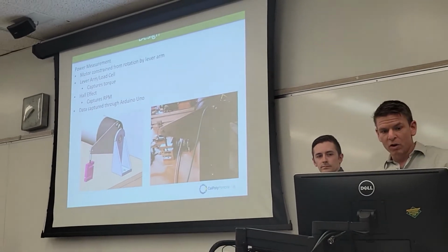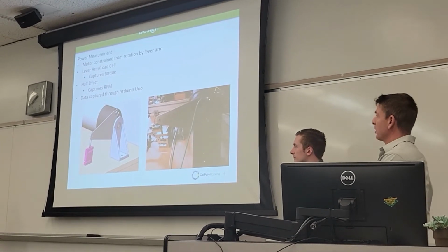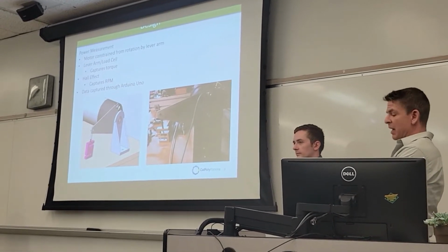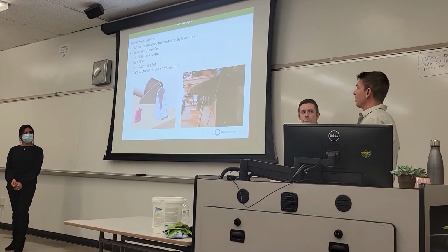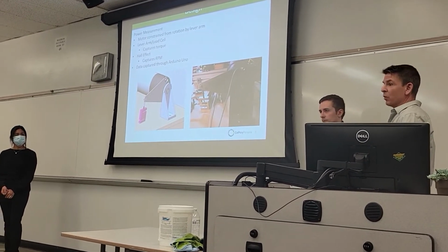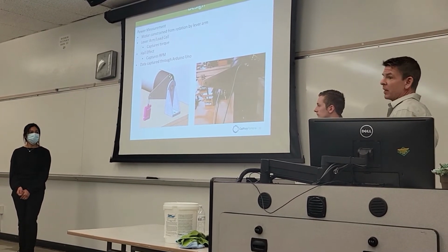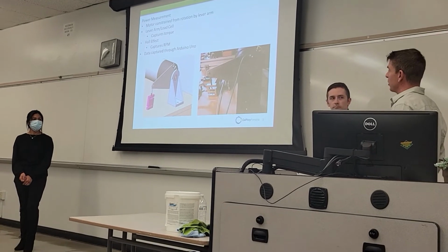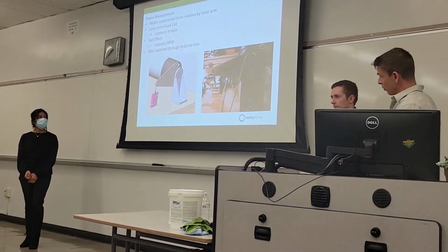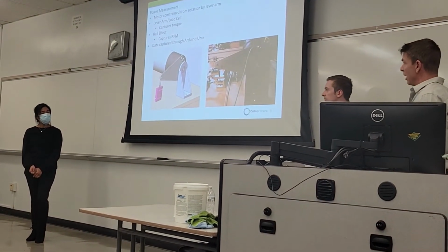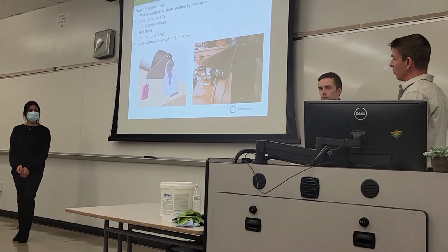Okay, so for our power, the way we're going to categorize the hysteretic losses is through a power measurement, and basically compare one tire to another. The delta in power would tell us which one's more efficient. And the way we're doing that is similar to the previous presentation: we mount our motor free to spin on the rear mount. And the only thing constraining the motor from spinning is the load cell right here.